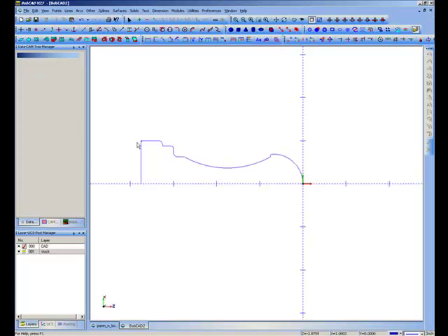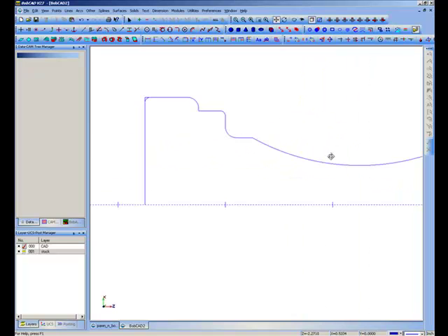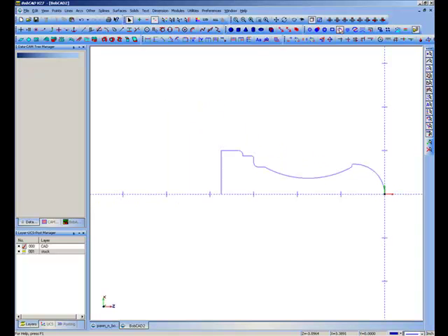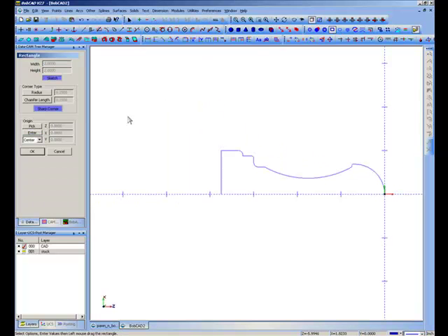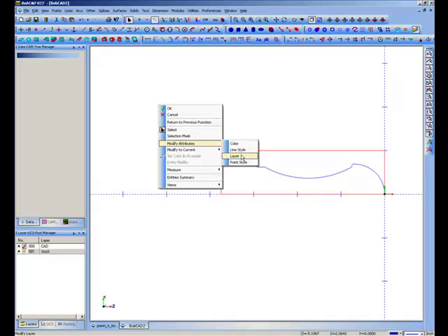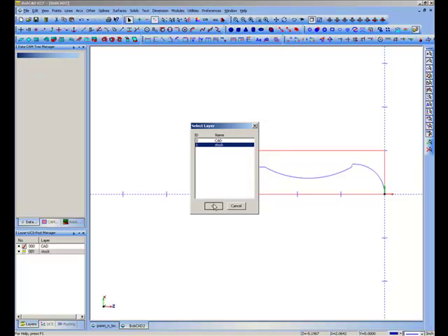Let's zoom in, and I can delete that one now. And now I can pick the square tool and just sketch. Shift click is what's bringing up those snap points, right? So I can shift click and poof. Now I have some stock geometry to define my stock with. I'm going to go ahead and get that on another layer right now to get it out of the way. Let's put it on stock.